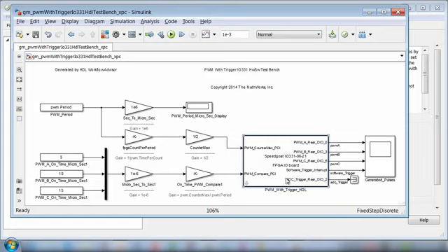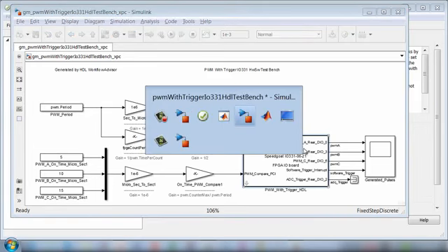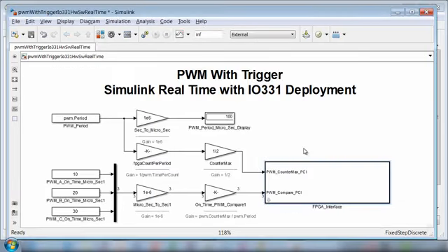Also, it left the output ports that I had in my original design, which actually got mapped to the FPGA pins. Those are now stubbed out because they're actually connected to hardware pins, so I don't need them to be present in this interface module anymore. So what we typically do, just to clean this up, is run a little script that strips these out. When I do that, I get a model that looks like this. Same thing as you just saw, but now I've cleaned out all those stubbed out ports and I just have the ones I really need to actually execute the design.